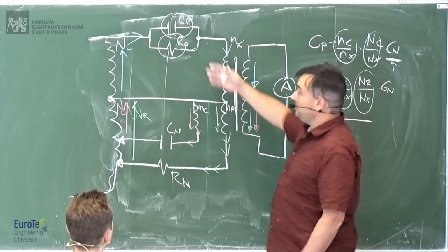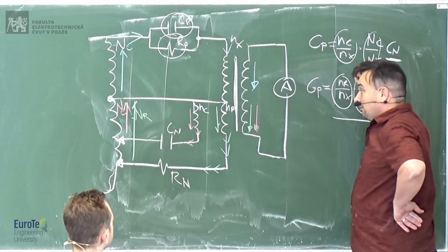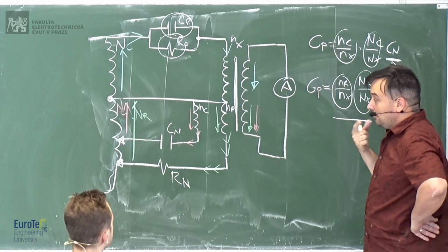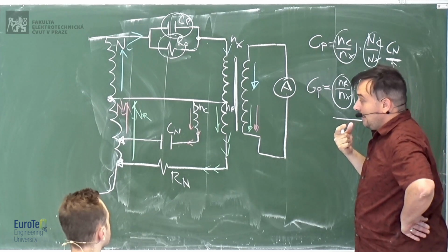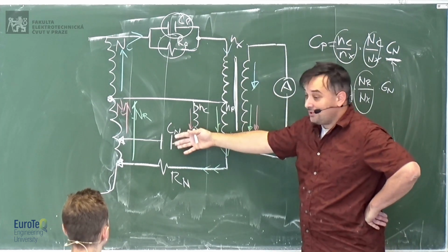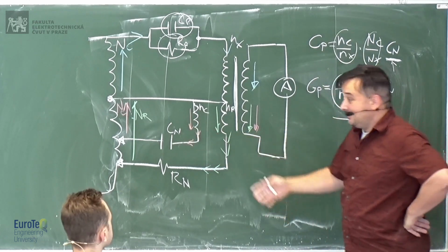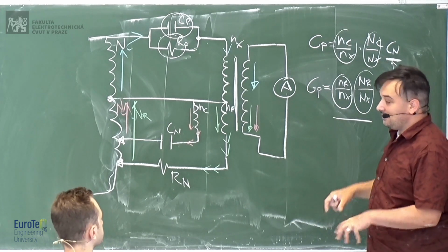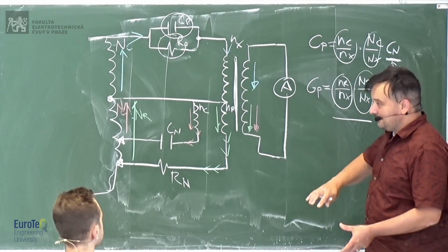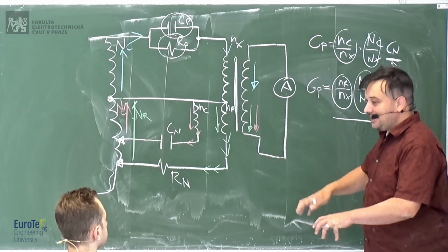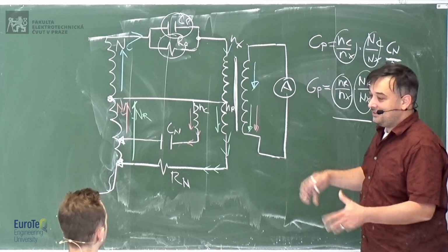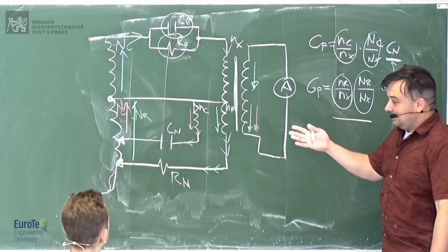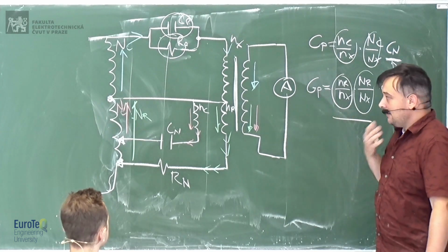So this is one of the methods that we use if you want to calibrate an impedance when you know that you want to have an uncertainty as similar as possible to the uncertainty of your standard. And if you have a standard, typically you don't have it tunable, because the fact that you have to tune it introduces some mechanical problems, which make also a lot more uncertainty, and noise. So if you have a good standard, typically it is constant.